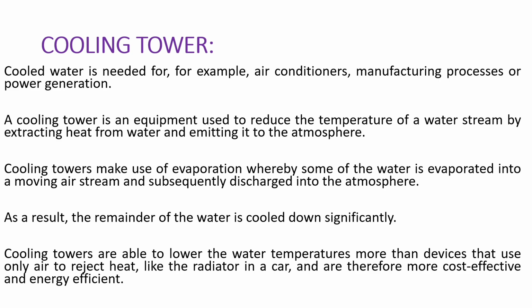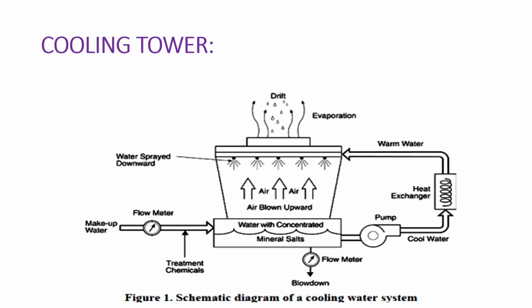The role of a cooling tower is to remove heat from hot water, and its principle is that some water evaporates into moving air, and this evaporation removes heat, causing the remaining water to cool down. And this makes cooling towers energy efficient and economical, because otherwise we would consume a lot of energy and electricity, so it would be energy intensive.